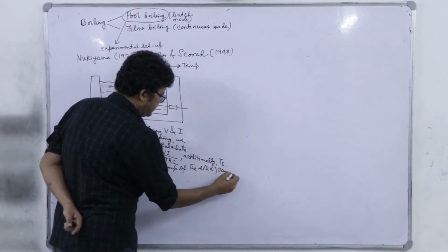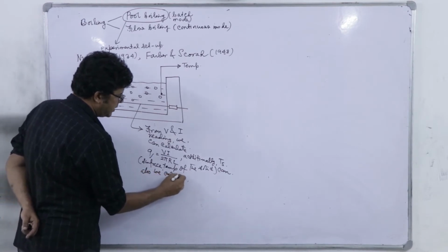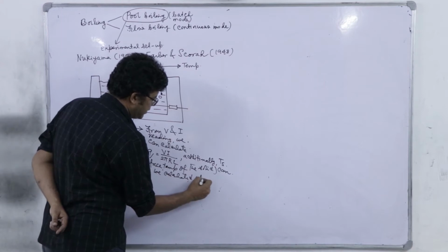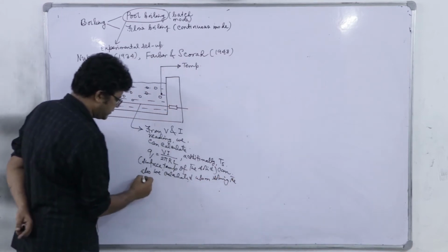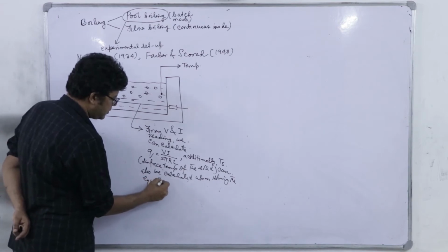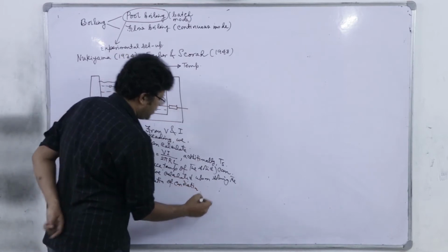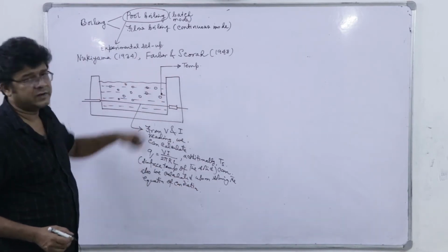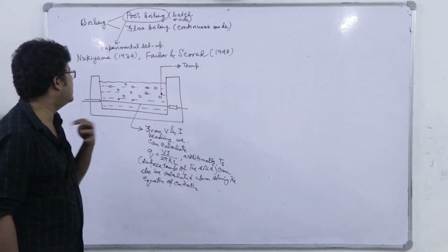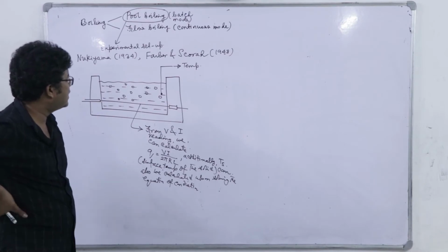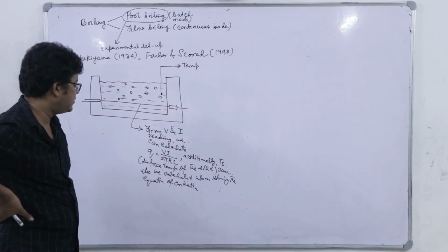can also be calculated upon solving the equation of conduction. Right, because far away the liquid temperature is known and this much heat is being dissipated. So, we can solve this conduction equation, and from there we can calculate the surface temperature.